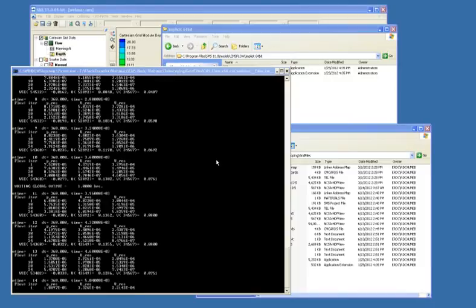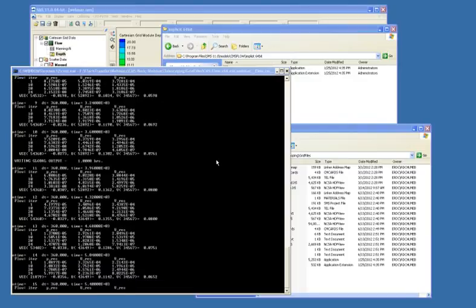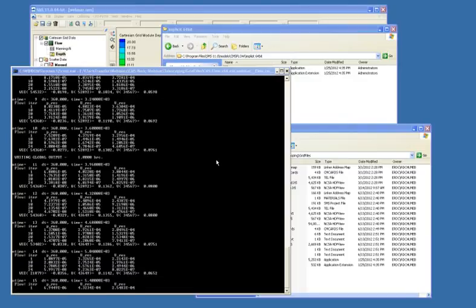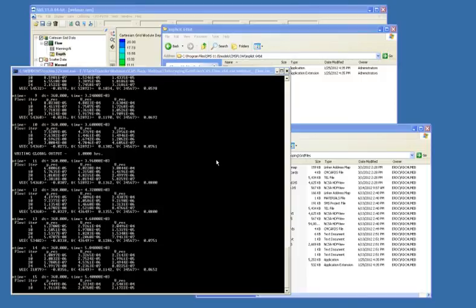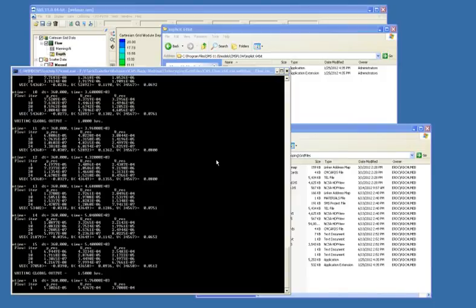Another question is, what is the difference between CMS Flow and AdCirc? AdCirc is another numerical model that can be used in many types of situations. It's more of a regional type model. So a lot of people use AdCirc to model deep ocean basins running with hurricanes.